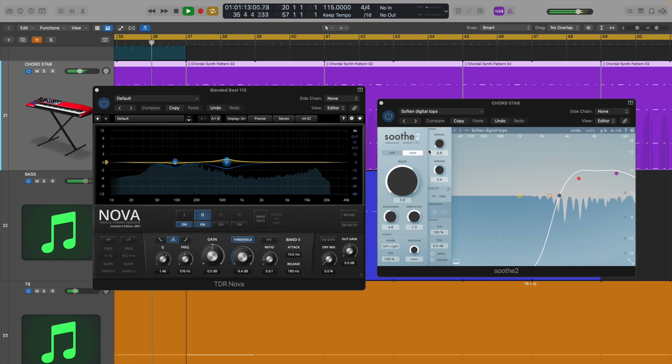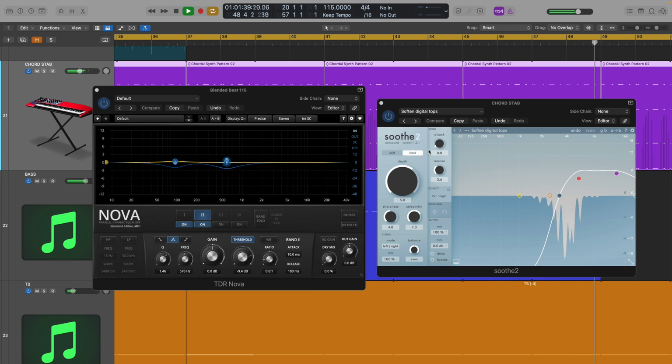Originally found in quite focused frequency-specific dynamic processors such as de-essers, over time the remit of these processors has widened with more accurate control over sidechain and target frequencies and both downward and upward processing. In the software domain, the result is a processor that looks a lot like a regular EQ, but is supercharged with additional dynamic functionality. And this provides a more focused solution than a multi-band compressor, which is better for broader